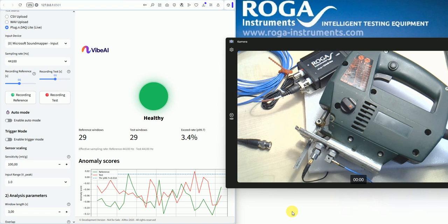On a scale which can measure 10 tons, you can weigh a big car. But if you want to weigh an item with 10 or 20 kilograms, the resolution of this scale with a measurement range of 10,000 kilograms will not be sufficient.